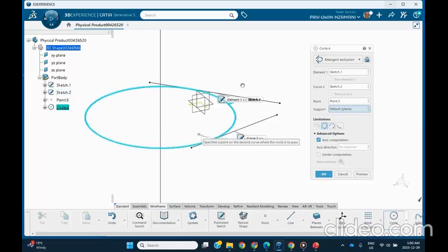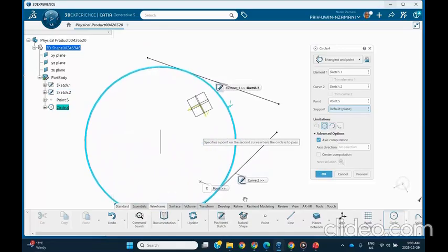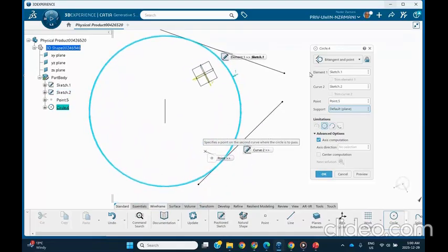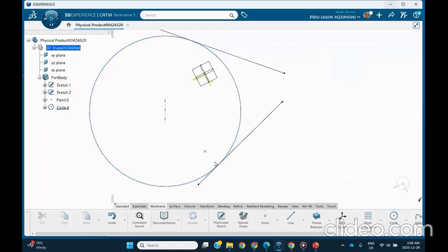You might say, well, what circle is this? Here's what happens. The definition of this bitangent and point is that this point is projected into that line, and you get the point down here. You see that? You get the point down here. Let me say okay. So this point is projected into that line, normal projection, and the circle is tangent to these two lines and passes through that projection point.